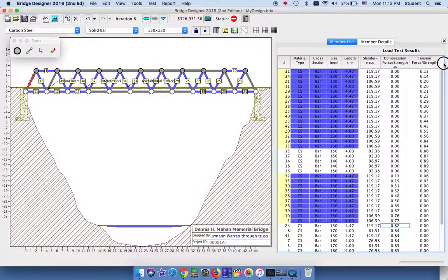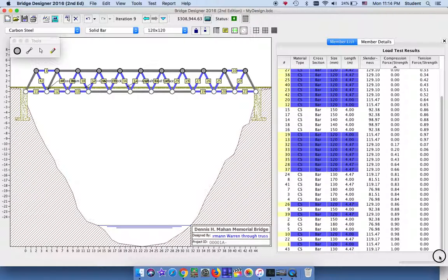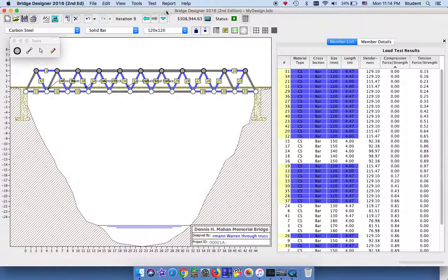So I'm sliding up, making these thinner. You can see it's displacing the weight anyway, and I'm at 308,000. So I'm looking here, deselecting here, and here, and I'm just going to continue optimizing my bridge. And so now you can see I'm at 293.